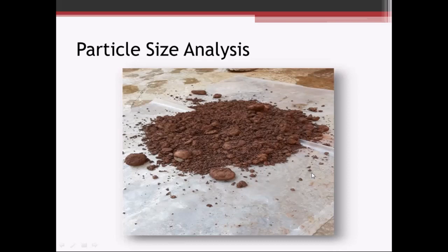And here's what we like to see for a structural fill or a sub-base material. This generally looks like a well-graded sandy gravel material. You can see the gravel size particles along with the sand size, the smaller particles going in between. From a sand and gravel standpoint, a well-graded sandy gravel.